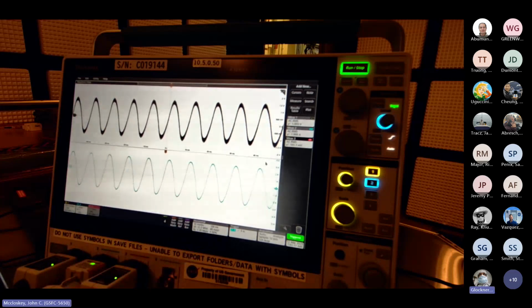So all right, write down our signal generator setting is minus 15.6. Voltage is 1.0015 now. And our current is 1.990. So it's still close to 2 amps, but it's coming down. So it's a little bit less efficient, whether inductance is starting to creep in and things like that. But anyway, that's 100 hertz.